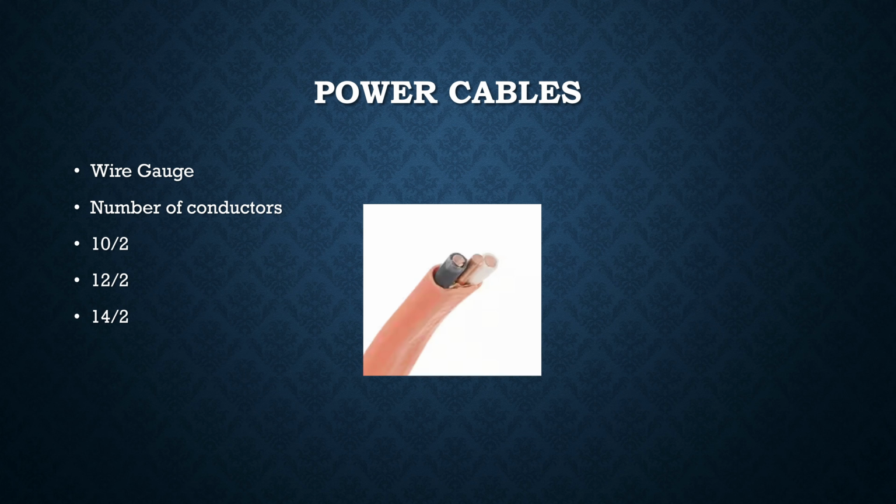And the way these wires are delineated is the first number is the gauge of the wire itself, right? So each of those wires in that picture, let's say it was a 10-2 wire, 10-2 Romex or 10-2 sheathed cable, whatever you want to call it, non-brand name. All three wires are 10 gauge, and two of the wires are designed to be conducting wires. So the center wire, that's the bare copper one, is the ground wire. That's just the safety wire, right?